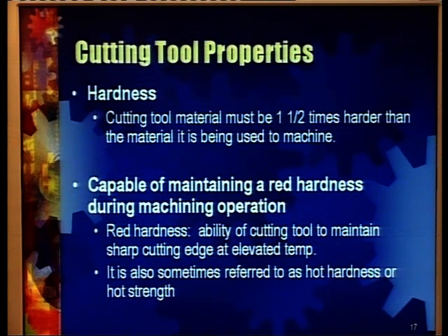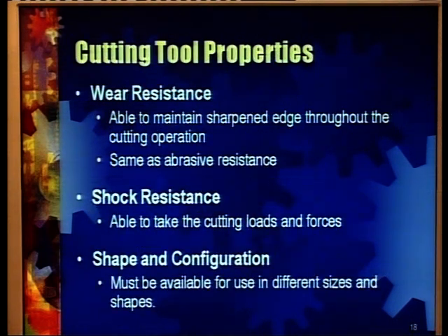Although we use coolants and similar arrangements to lower the temperature of the cutting tool as well as the workpiece, still the temperature in the cutting zone is very high. So, it is very important that the tool material should be able to withstand high temperature.